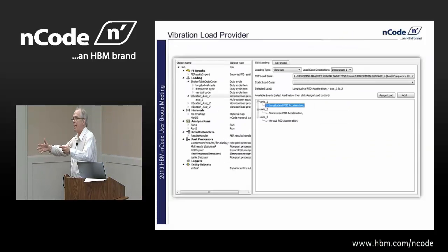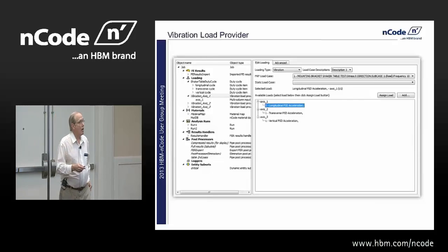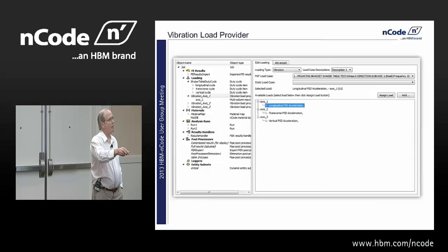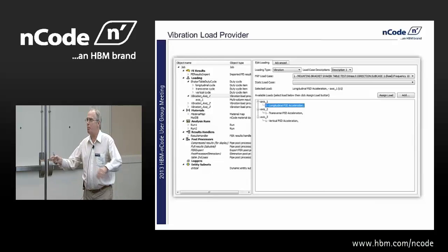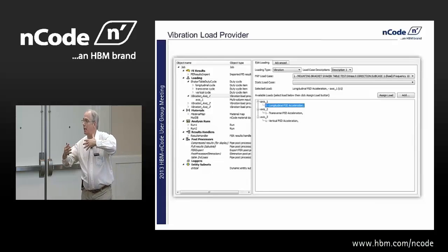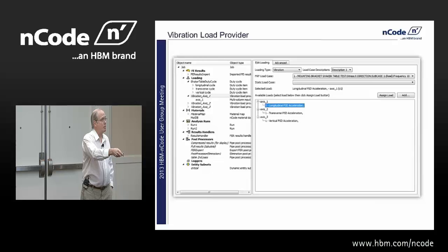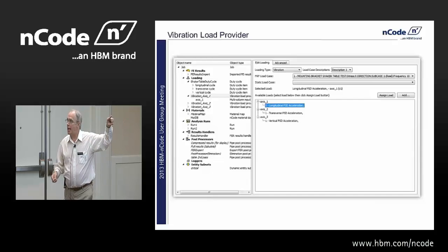So those go into DesignLife, and then like any other analysis, we have a load provider. And the load provider for vibration, basically we have an upper entry that just points to the harmonic analysis or the steady state dynamics analysis that we're bringing in. So we bring that in. Down below, we have available any of the PSDs or swept-sine signals that were specified, and we basically just pair these two up. And then in the center, we have the ability to point to an additional FE input that would be the static stresses.